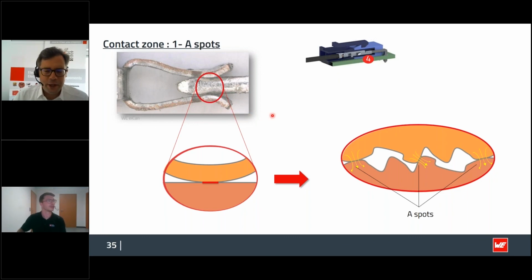I just wanted to say one thing that came to my mind, where we have a contact between stainless steel and nickel, and that is for the shielding of USB connectors, for example. Here we have stainless steel in combination with a nickel plating. If you think about a connection between a USB-A type male and female side, plug and receptacle, in this case about the shielding, we have a combination of stainless steel and nickel plating, and that's also a reason why it is mentioned. That's just one thing that I wanted to add.